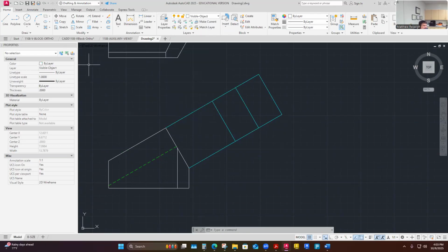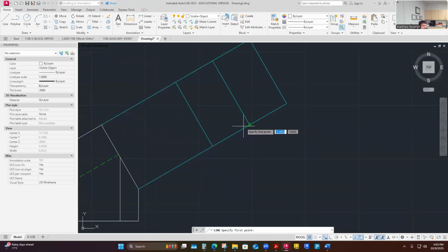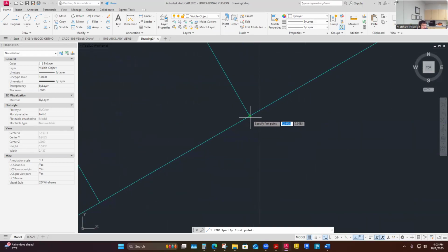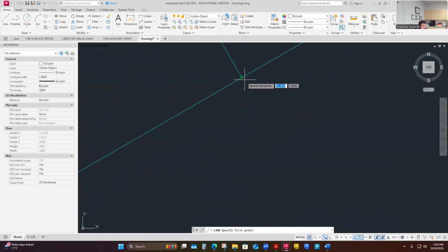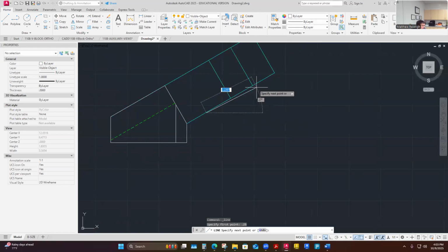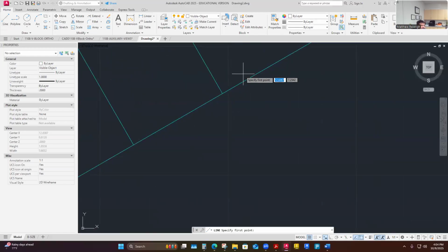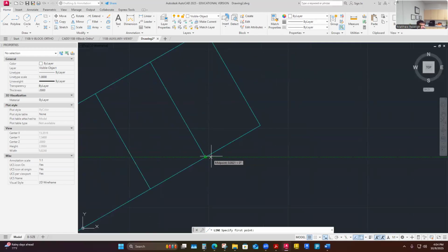Let's do some visible line work. So right here, that little surface, I'm gonna make sure I grab that on the midpoint. Good, good. I just want to make sure I'm grabbing it accurately. I'm gonna cursor over that 0.25. It had me grabbing a different view. Let me try that again. Just cursor up 0.25, and then I'm gonna go back by 0.5.